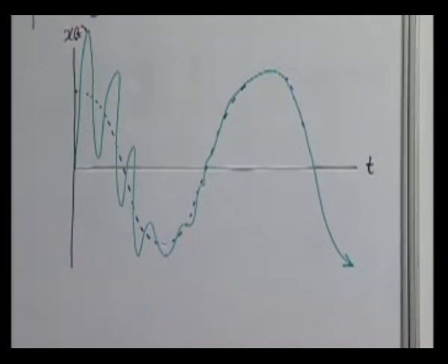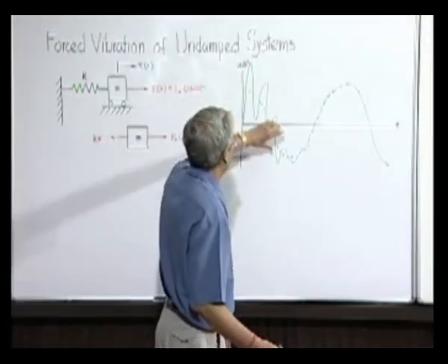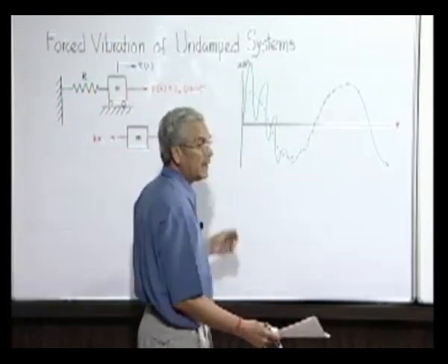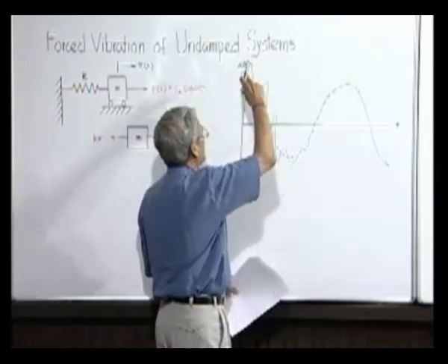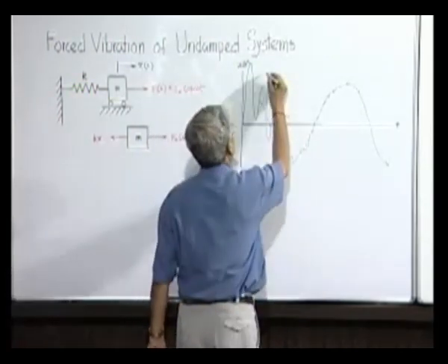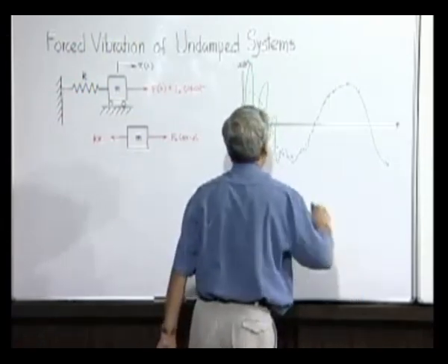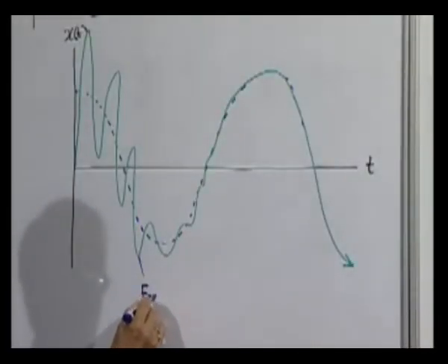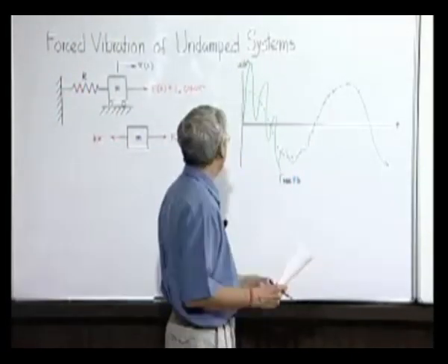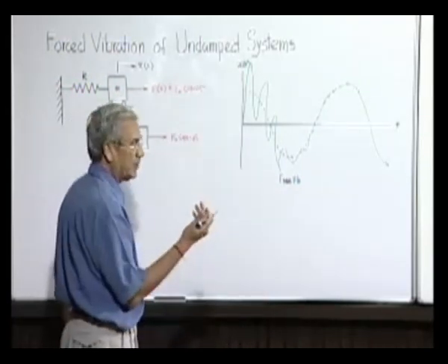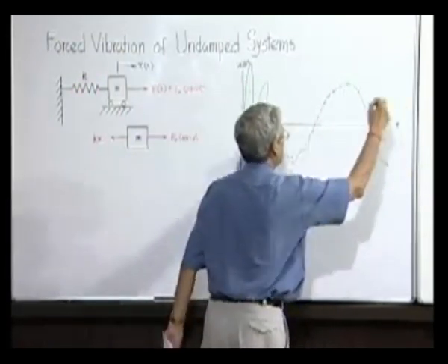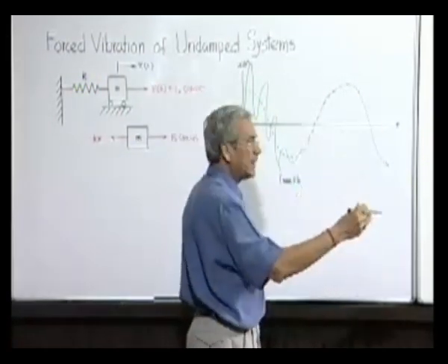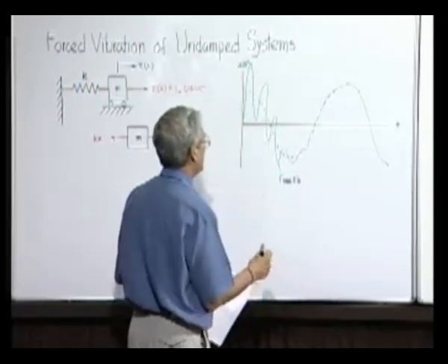Of course, I have shown this taking a short time, but in reality it may continue for a large time. Eventually the initial free vibration part, that means this is the free vibration part, will gradually damp out, and what will remain is only the particular integral. So the response in the steady state situation, that means which will keep on maintaining its nature and character, is called the steady state.